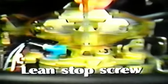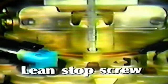coolant temperature. This diagram shows the position of the mixture control solenoid inside the carburetor. Solenoid adjustment is made by a lean stop screw, which controls how far down the paddle will travel when the solenoid is engaged. There is also a rich stop screw adjustment that controls how far the paddle can go up when the solenoid is de-energized.